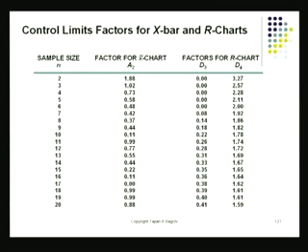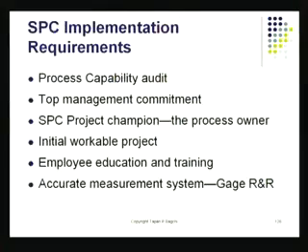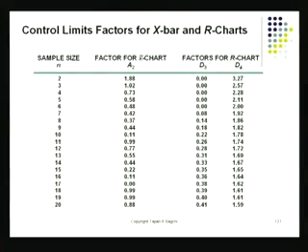Something you got to remember when we talk about control charts, and you can't really throw this away. We are constructing the control charts to be able to get signals out of them. And signals are basically indications of major process disruptions. And this is being done online, that means as close to the actual time of production as possible, so that you can take corrective steps very, very quickly.